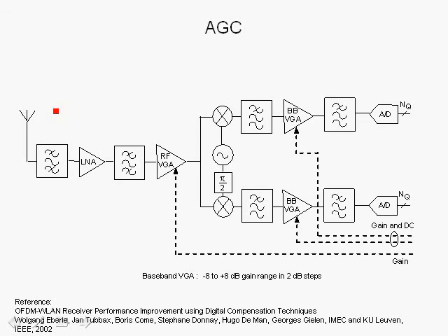However, if we have a strong signal coming in, then we will exhibit saturation on the analog to digital converters and also saturation in the receive chain. In that case, we have to start peeling off the gain when we have high signal to noise ratios. So initially for high sensitivity we set the gains to maximum. However, when a signal with a high signal to noise ratio arrives, we have to immediately start peeling off gain, and that is done by observing that the A to D would start to saturate, or we have a threshold for the RMS at the A to D output.